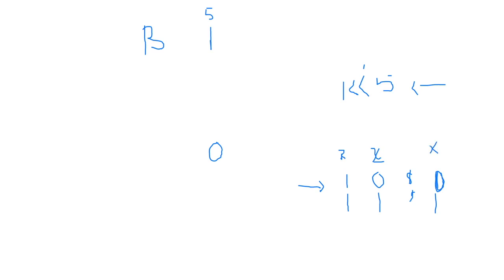Then we say, okay, we managed to read the actual state of X. We simply have to NOT it or just invert it. So we use that, gain the value of the state of X, and then we invert it. So if we, let's say, cross out this stage, we notice that we move from 0, end up with a 1, and when we move from a 1, we end up with a 0. So previously, just as we read the state of X or the signal with an AND, now we read the state of that signal, and then we simply use an AND NOT gate to invert it.